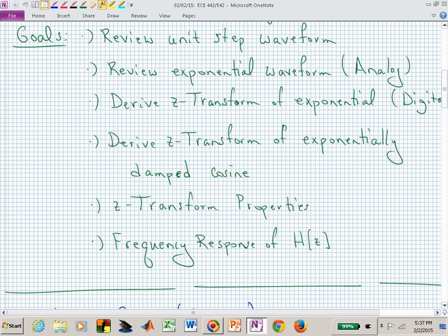If you said, where are the poles associated with this waveform in the complex S-plane, and it's a sinusoid or a cosine, a sine or a cosine, I'll just maybe say a sinusoid, where would those poles be located? Do you remember? If you Laplace transformed a cosine, where would the poles of that transformed waveform be in the S domain? Pardon? Off of the real axis. Now I want a pure sine wave, on the imaginary axis. That's where they are in the S-plane.